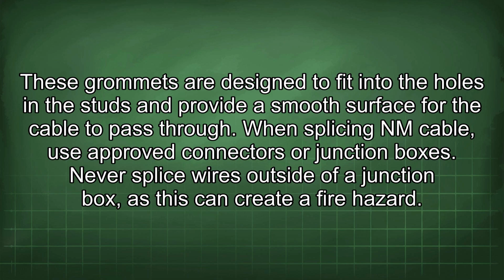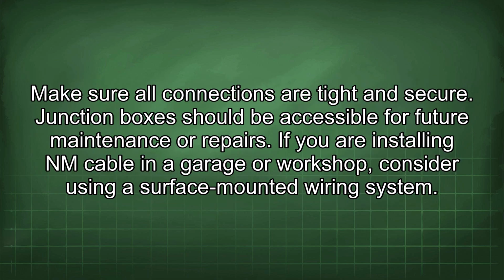to pass through. When splicing NM cable, use approved connectors or junction boxes. Never splice wires outside of a junction box, as this can create a fire hazard. Make sure all connections are tight and secure. Junction boxes should be accessible for future maintenance or repairs.